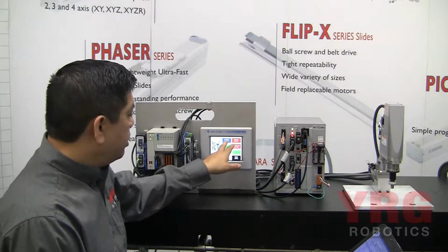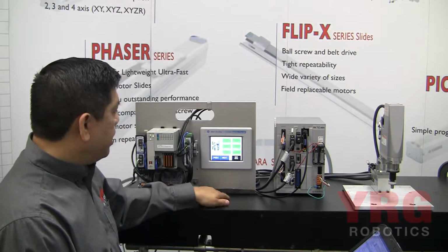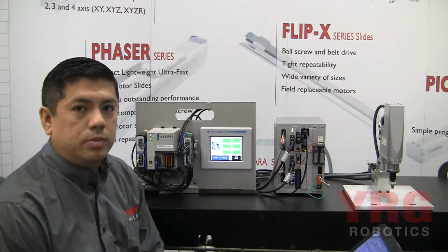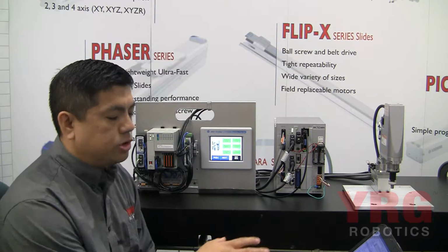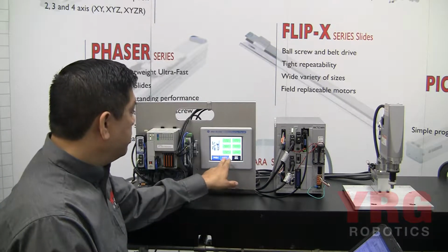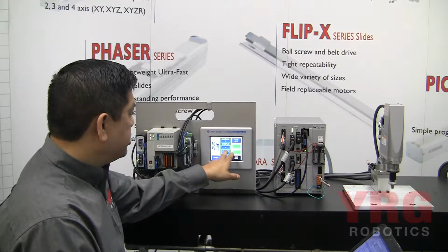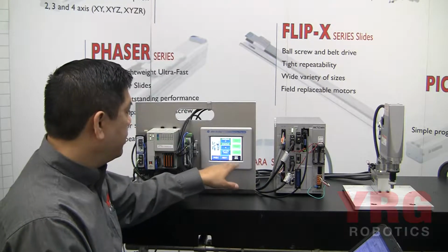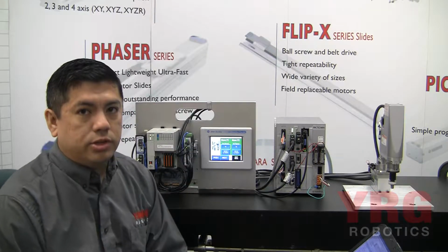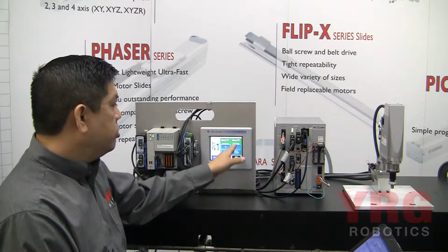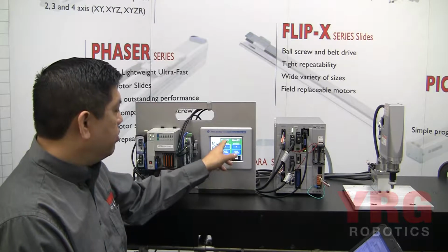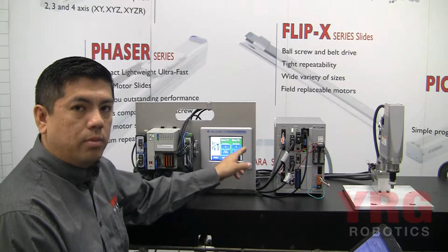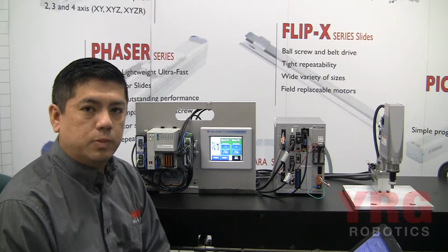I'll go ahead and turn my robot on. I'll power it on. And I have a Panel View here to assist me via LadderLogix, and I'll also show some LadderLogix here. So I'm going to go to the next screen, and I'll set my speed to 15% so I don't hurt myself, and then go into auto. My first demonstration screen basically has two different screens where I can move the robot to point 1 and move the robot to point 2 at a certain speed.